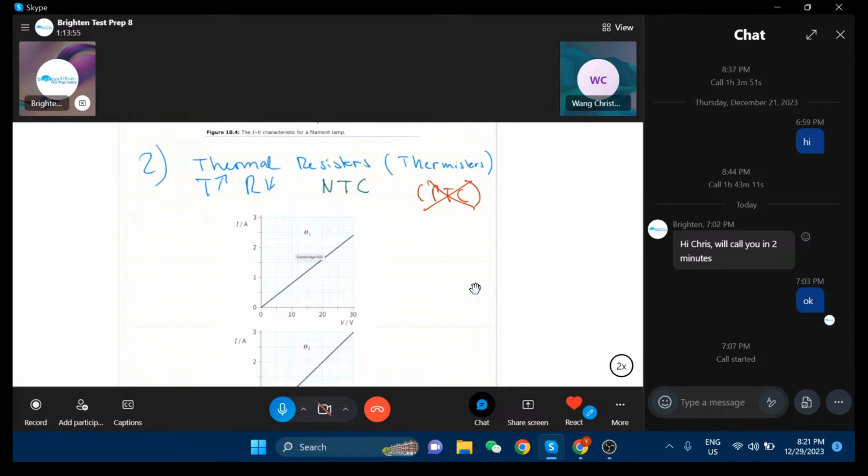The thermistor resistance decreases. That means the current increases because of the decrease of the resistance, and that overloads the circuit, which then cuts off. So it's like a double stage security measure, actually, that the drop of the resistance increases the current. And because the current goes into overdrive, so to speak, the fuse reacts to that and shuts it down.